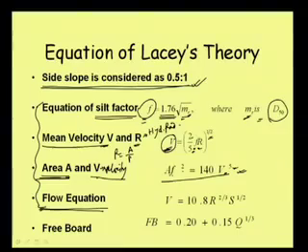But here in Lacey's formula, rather than 1 by n, the other part remains the same, R to the power 2 by 3 S to the power half. This part remains the same as Manning's formula, but he gave a value 10.8.